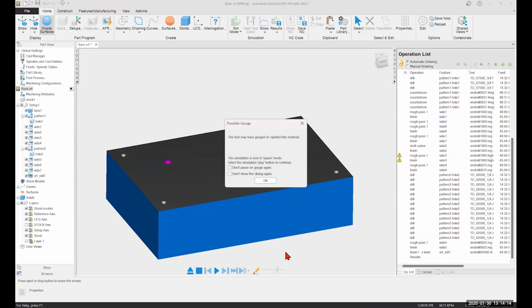That's why you saw that progress bar at the bottom, showing that it was calculating 3D toolpath. Now, again, some warnings come up here, possible gouge, and it looks like there's the gouge there. What's happening here is that it looks like a center drill has gone before a pocket's been created for some of those lower holes. So let's take a look at that.